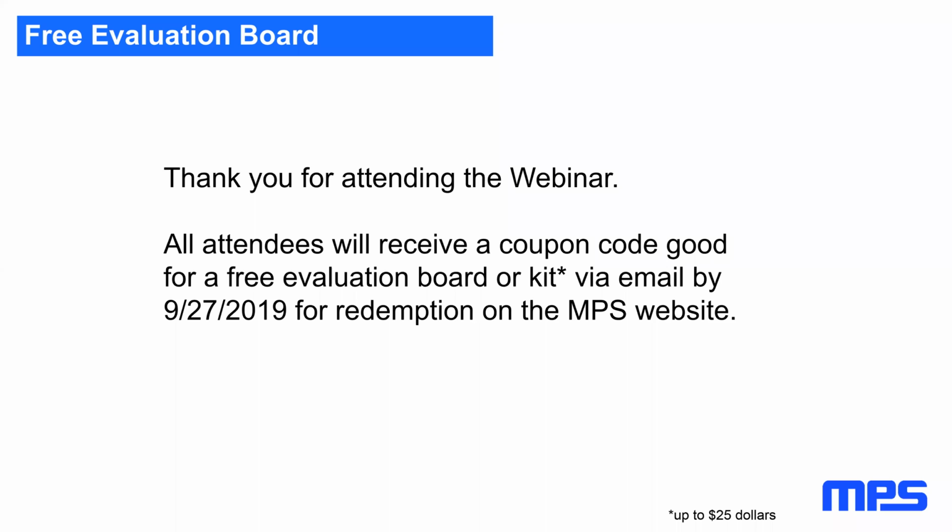And to reduce the EMI, is it better to use a via for a decoupling capacitor? A decoupling capacitor should always be put on the top side. There's a rule of thumb: if you go through a complete PCB, it's about 1 nanohenry per via. So you destroy the performance of decoupling capacitors if you push that current through the inductance of vias. Always put decoupling capacitors directly on the side where the traces are that you want to decouple. So don't use vias if you can help it.